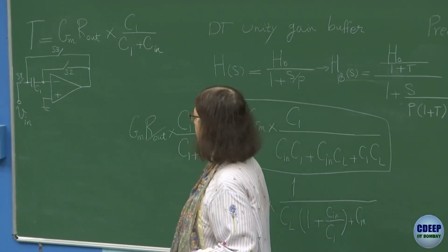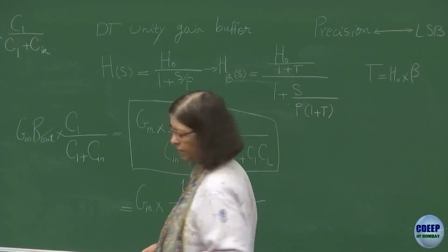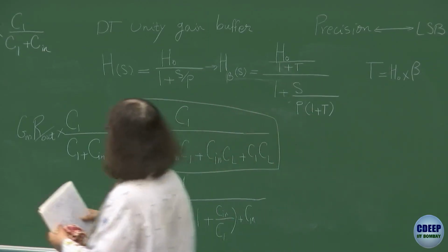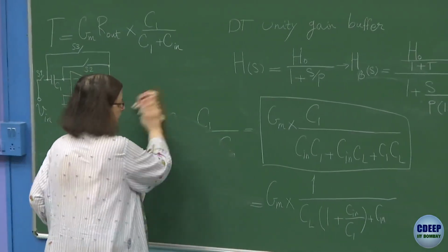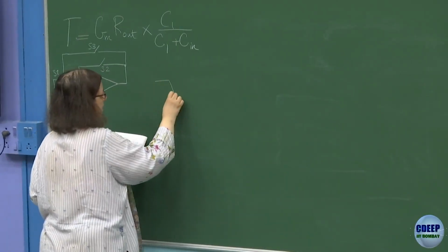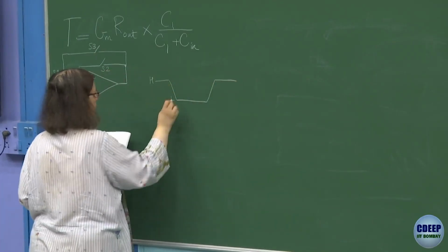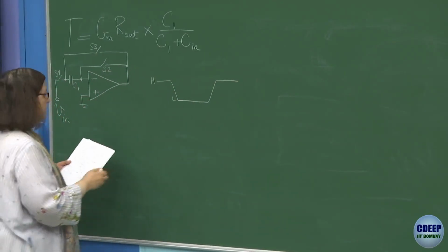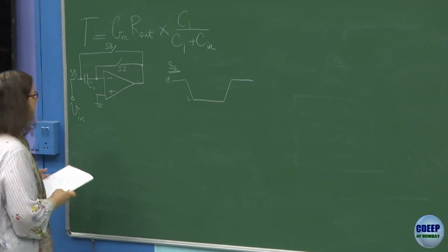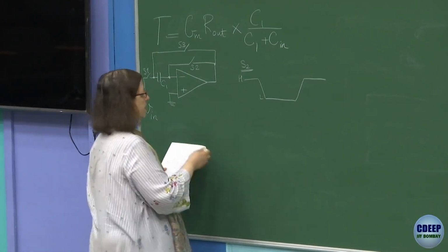Okay, and the sequence we also discussed. I thought it would be good to draw the control signals for the switches, based on the arrangement we decided last time for reducing the effect of charge injection. I start from the time S2 turns off. This is logic high, this is logic low for the clock phases. This is for controlling S2. First S2 turns off and then S1 turns off, and S3 is already off.